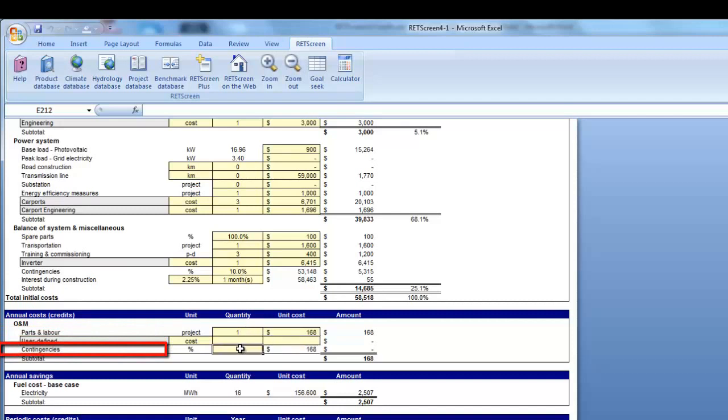A contingency allowance should be included to account for unforeseen annual expenses and will depend on the level of accuracy of the operation and maintenance cost estimate section. It is common to carry a contingency allowance for at least the replacement of the most expensive component subject to catastrophic failure. Considering the durability of PV systems, an annual contingency allowance of 1 to 5% is a reasonable approximation depending on the project site. Since the yearly O&M costs are quite low, we will consider a larger contingency value of 25%. At this rate, the O&M cost would increase to $210 per year.